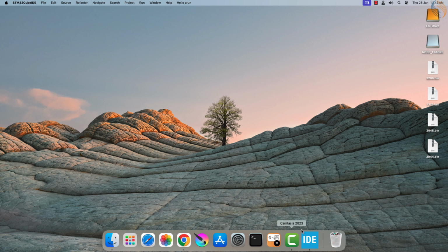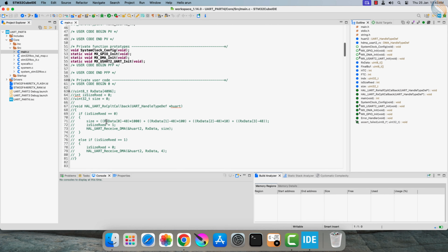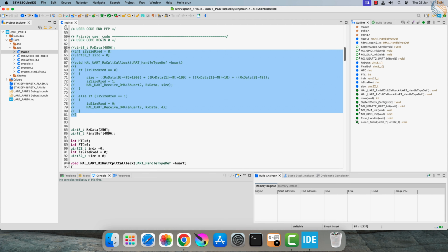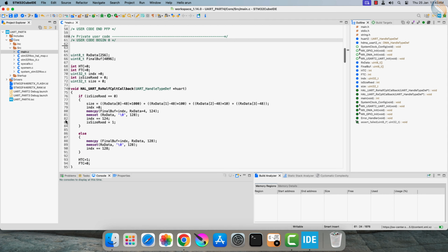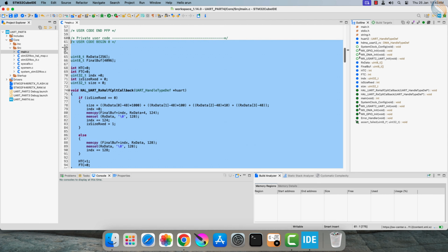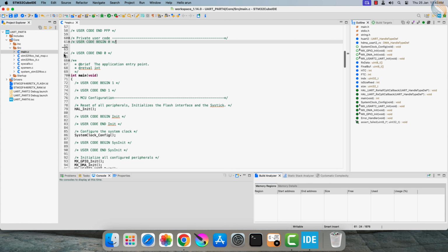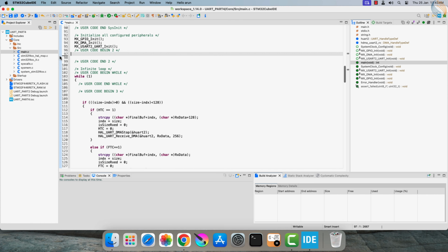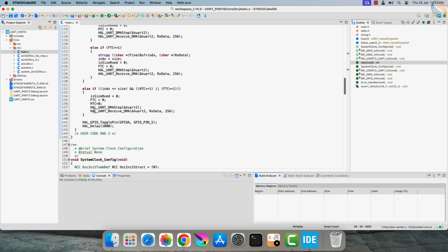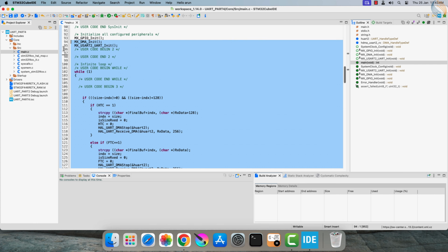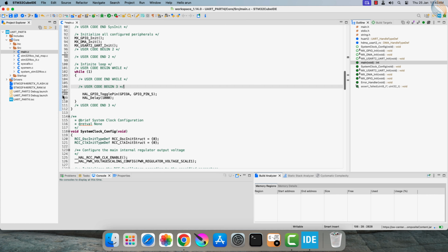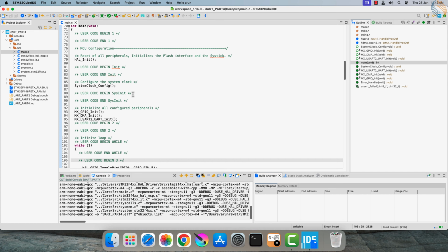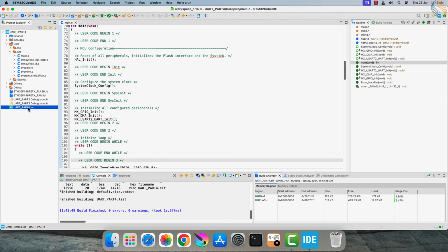When the peripheral detects this idle line, it can trigger the interrupt, or exit the blocking mode, depending on how we are receiving the data. In today's tutorial, we will utilize this idle line feature of the STM32 to receive the data of unknown size. The advantage it has over the DMA method we used in the previous video is, this time we won't need to send the size of the data. We will extract the size from the received data itself.